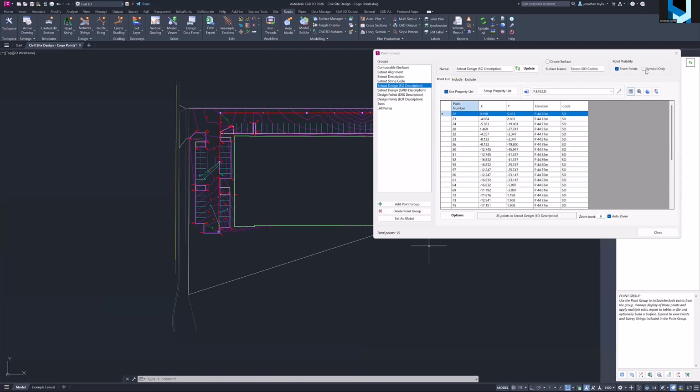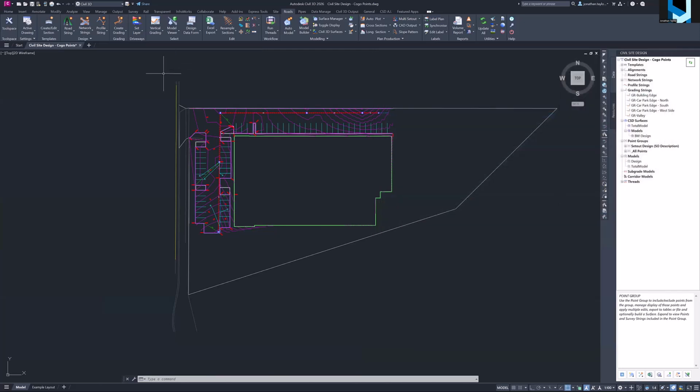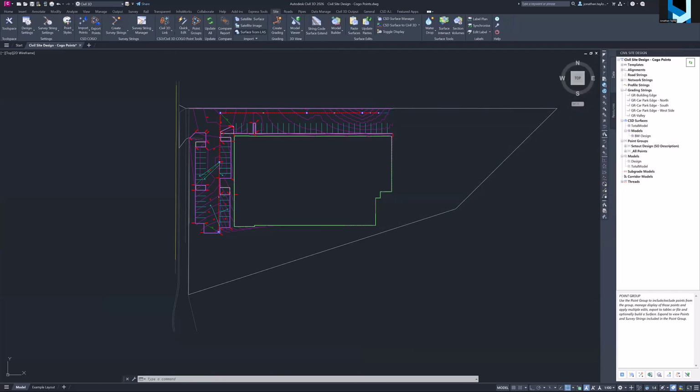Bear in mind, everybody, this is a beta, so there may be something that's not working. Great disclaimer, Todd. Not 100% sure, and this is not something I've spent a whole heap of time doing. It is not normal behavior. But yes, it is possible. So you can take a collection of points out of a point group and pump it out into a table in the drawing.